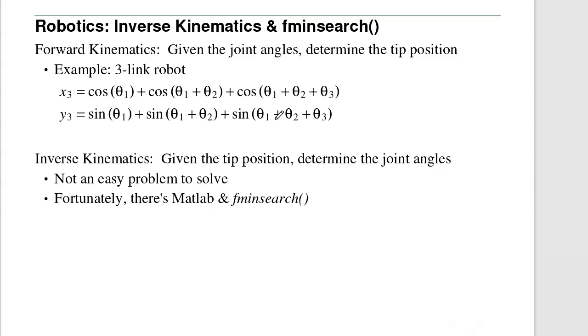Now this is kind of where algebra fails you. Given x3, y3, solve for theta 1, theta 2, theta 3. That is not easy to solve. But fortunately, there's a program in MATLAB called fminsearch. fminsearch is a really useful program that can solve all sorts of problems, including this one.